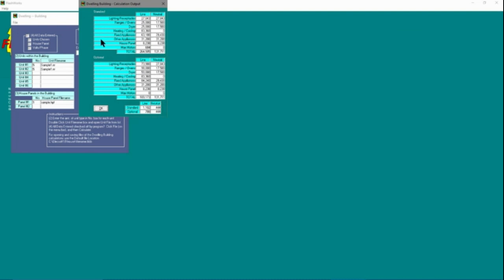Your total load for the standard line load is 264,505 volt amps. Your neutral is 131,711 volt amps. Optional, now this takes the optional deductions for heating and cooling and all the optional deductions from Article 220. And notice that the load down there is 189,173. Neutral's the same. And then we pick a panel.